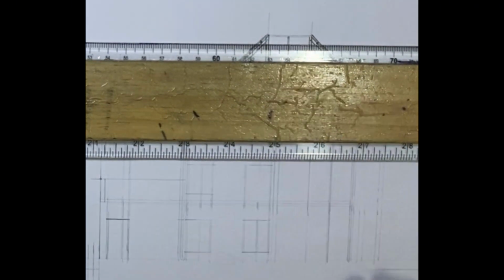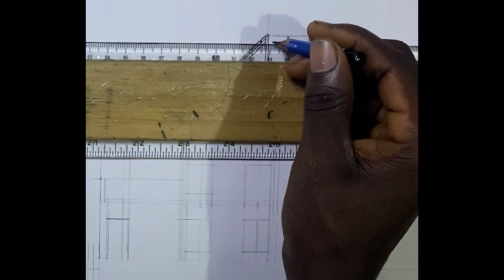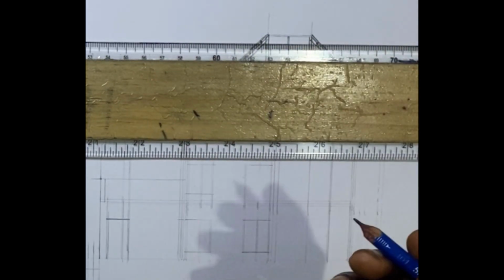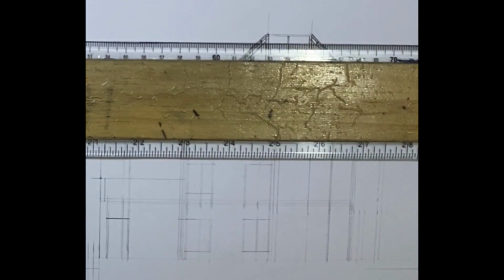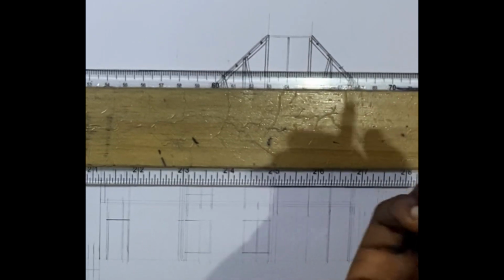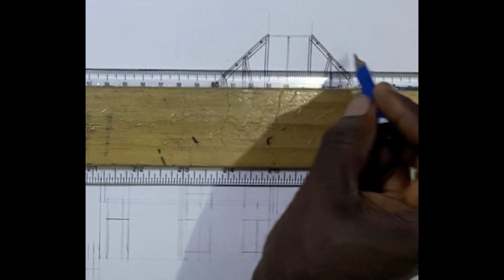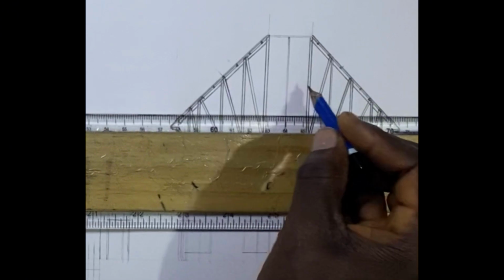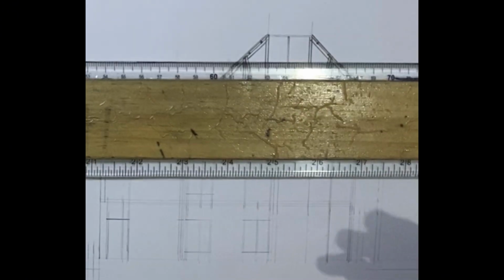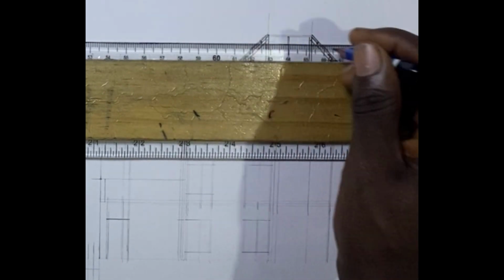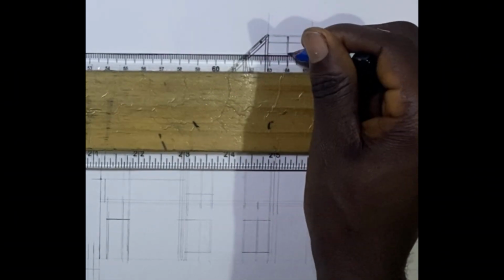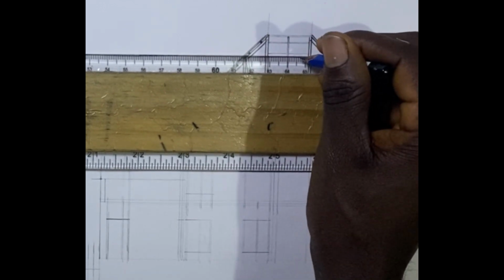So the purlin right here is also 50, but this time in the longitudinal section, and it's drawn faintly. You can just project your purlin from the other one we've measured, the 900 center to center, this time making it longitudinal, just behind our king post.